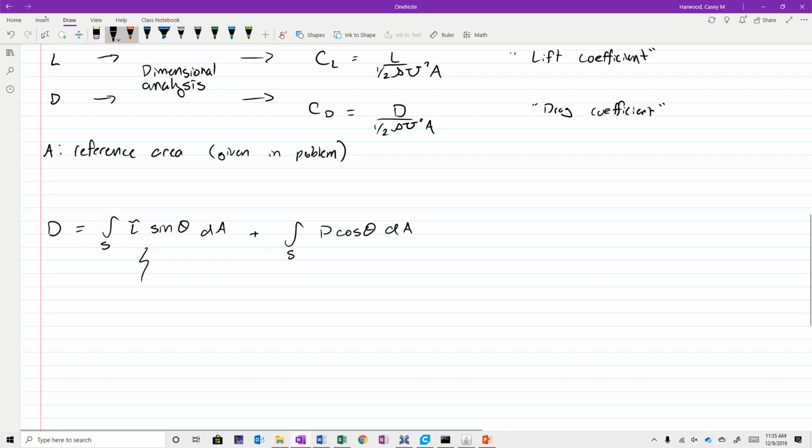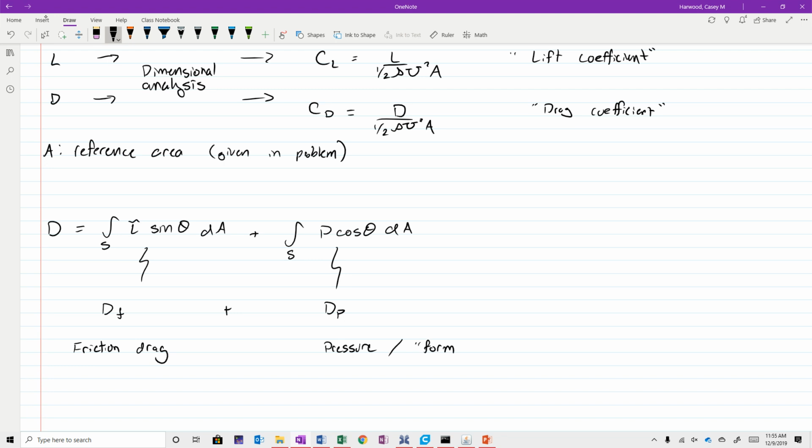And this first term, the one involving the shear stress, we're going to call D sub f. And the second term, we're going to call D sub p. Friction drag and pressure, or what's known as form drag.